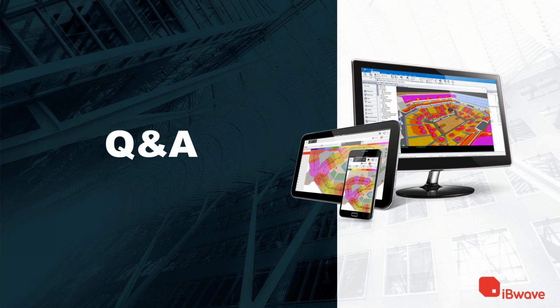Yeah, the mobility part, I think it's really important because LTE is much more efficient in handling what in Wi-Fi we call roaming, in cellular we call handover. Compared to Wi-Fi, when you're moving, you have to disconnect from one access point to another one. In LTE, you don't need to do that. You could connect to a small cell at the same time and then switch from one to another. You could actually use carrier aggregation and connect to 3 small cells at a time on 3 different channels, and have, let's say, three times the throughput since you're connected on 3 different channels at the same time.